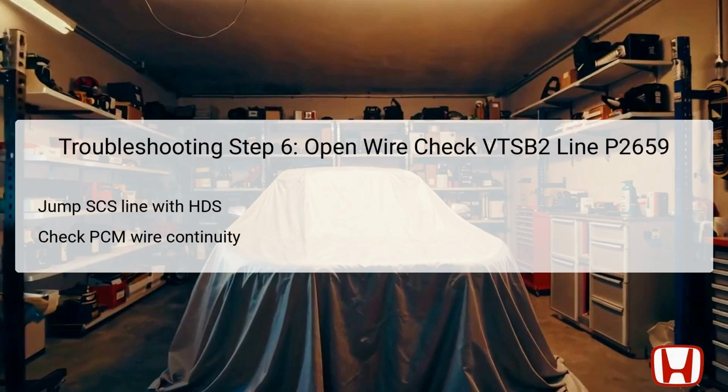The final step in the troubleshooting process involves checking the continuity of the VTSB2 line. The technician should begin by jumping the SCS line with the HDS, allowing more than 1 minute for the systems to stabilize. Following this, the connector to the powertrain control module, PCM, should be disconnected. This step is vital because it isolates the PCM from the rest of the vehicle's control systems, allowing for a